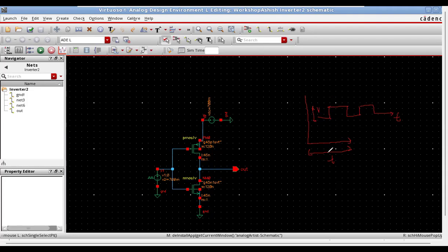When you are talking about the DC analysis, it means in the x-axis you are having certain voltage. You can have anything in the y-axis. It can be a voltage, it can be a current, it can be anything. But in DC analysis, in the x-axis you will surely have a voltage, and in transient analysis on the x-axis you will surely have the time, right? And it is you who is to decide how much time. Now let me explain you why.